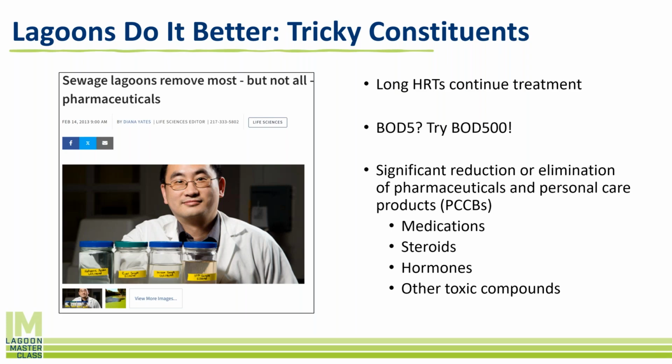So we're not looking at just BOD 5, how much BOD do we remove in 5 days? Lagoons have BOD 500, BOD 1000. When those solids settle out into the sludge, that sludge sits there for 10, 20, 30 years and has a very long time to break down.